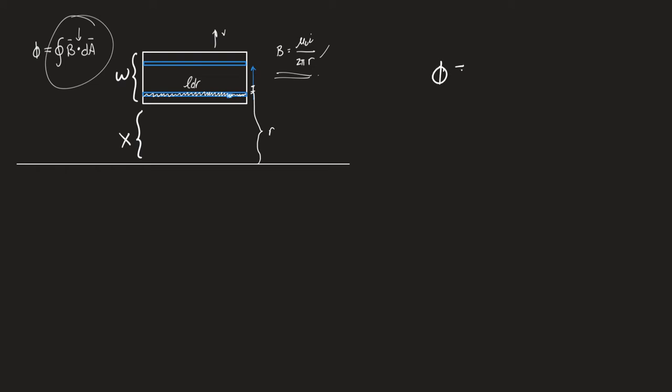So help me out. When we were done, there's an expression for the flux here. And I know probably mu naught I over 2 pi is out front. What's the rest? Go ahead. Mu naught I L, so that's outside the parentheses. And in the parentheses, if you leave it in terms of x, it's ln of (x plus w) over x. Is that it? Any mistakes I've made? Anything I left out? Because I'm not re-deriving it and I don't have it memorized from yesterday.